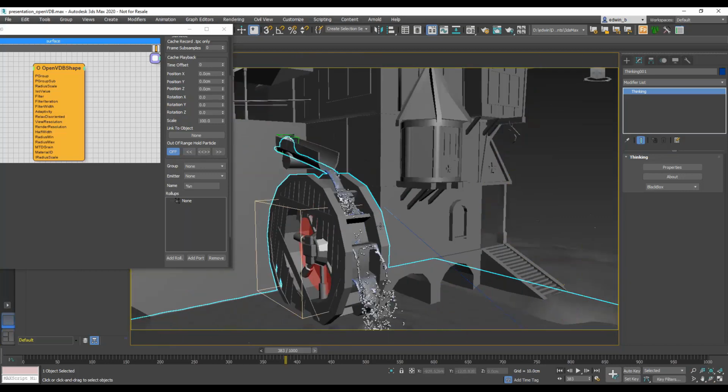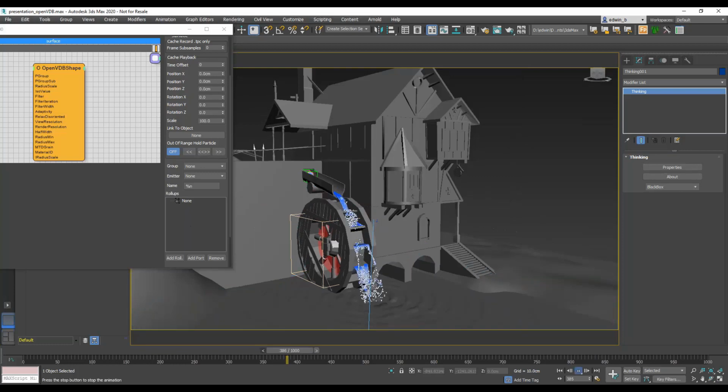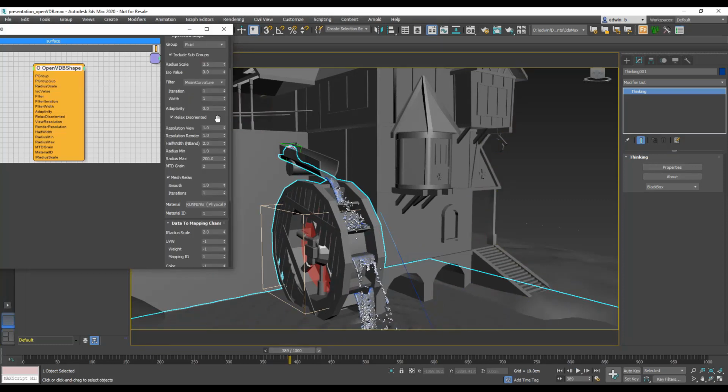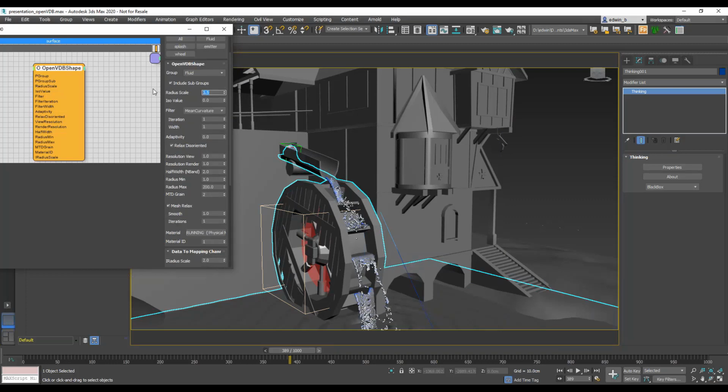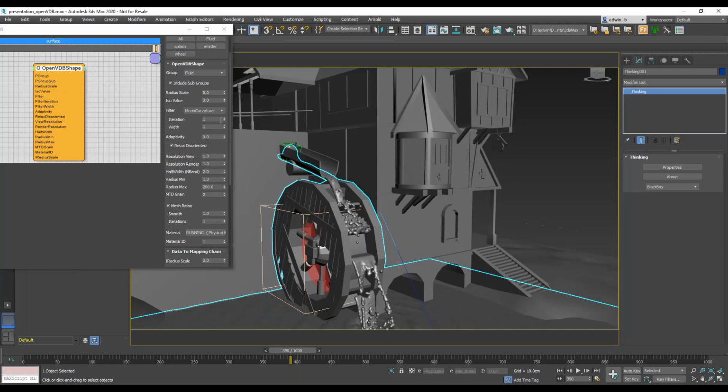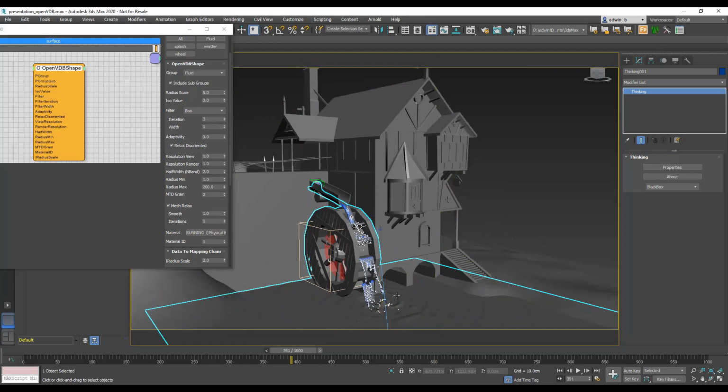Let's turn this on, so we now created the surface. With every step, we now actually also get a surface created. And let me just zoom in. So you see the surface here. We could also adjust the surface really nicely. If I wanted to have a better connection between all these little droplets, I like the droplets, I don't want them to be that blobby, but again, you can adjust here, do the resimulations, and then you get real nice water sheets.